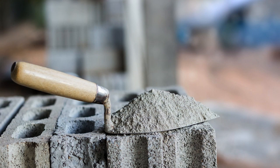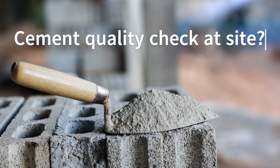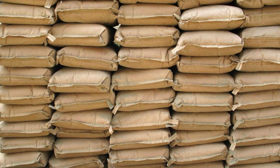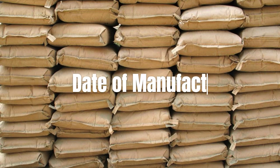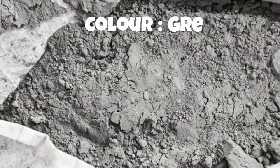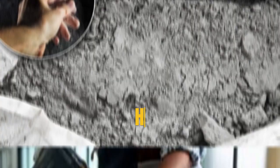Question 2. What is the procedure to check the quality of the cement on the construction site? Answer. At site, the cement quality should be checked as follows. Date of manufacture. Cement should be used before 90 days from the date of manufacture. Color. The cement color should be gray with a light greenish shade and it should be uniform. Float test. Good cement sinks and doesn't float if you throw the cement in water.